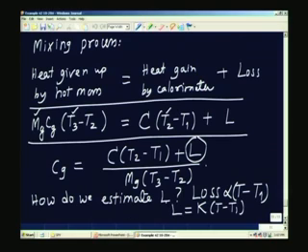In fact, the question now is how are you going to estimate the loss, and we will make a simple assumption. Because the temperature difference between the calorimeter and the outer vessel is kept very small, we can assume that the loss must be proportional to the temperature difference between T and the jacket. The jacket temperature also happens to be the initial temperature of the entire system. So, we will assume that L, the loss from the calorimeter, is proportional to some constant K times T minus T1. So, now let us see what is the consequence of this.